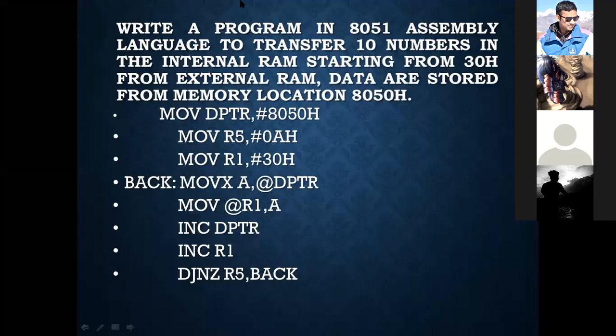So same operation is going on because DPTR is located at 8051H. So 8051H content will be moved to the accumulator, and accumulator content will be moved to 31H memory location. Clear or not? And this loop will continue until this R5 will be 0. And when this will be 0, this will be the end of the program.